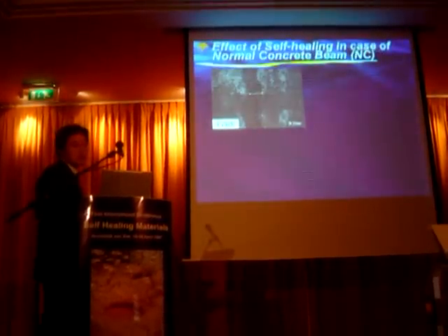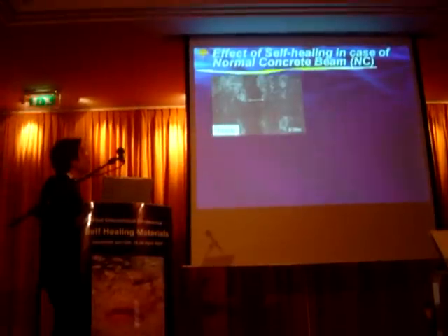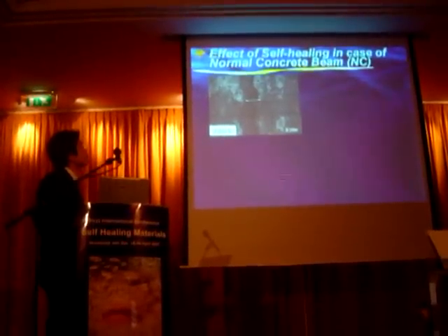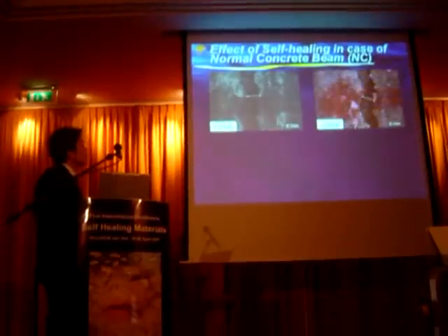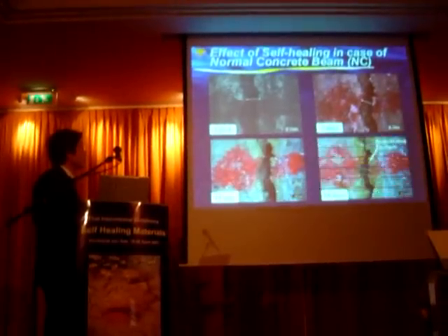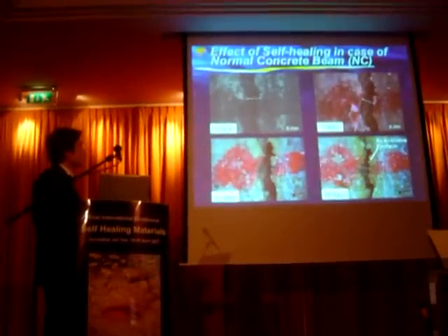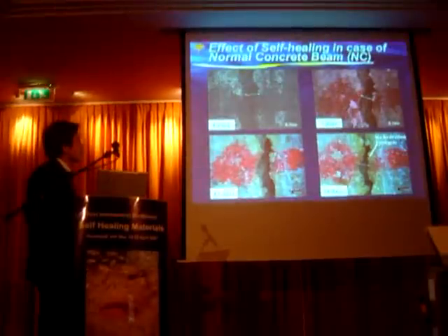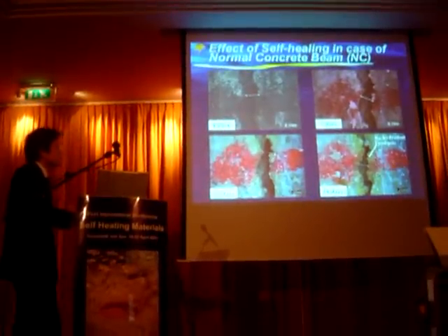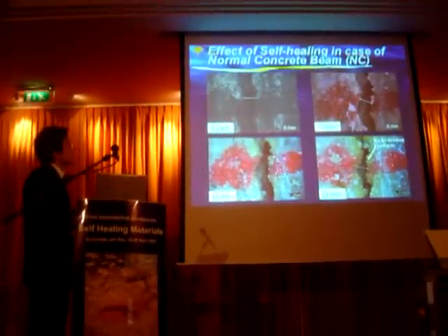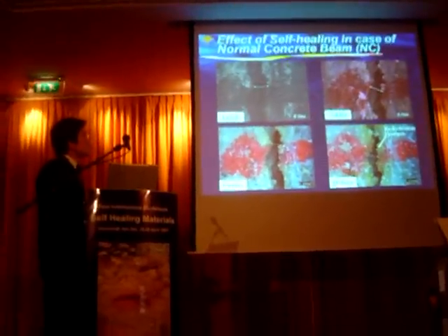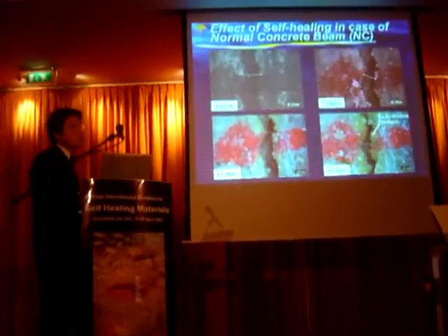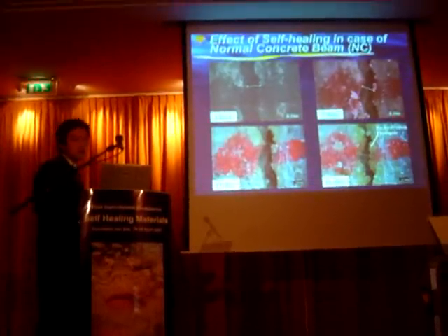In the case of the normal concrete beam at the low water to binder ratio, the crack was also closed by rehydration products until 28 days. However, you can find different ratios of self-healing ability between the two concrete beams. So in order to clarify this phenomenon, we did the test as follows.